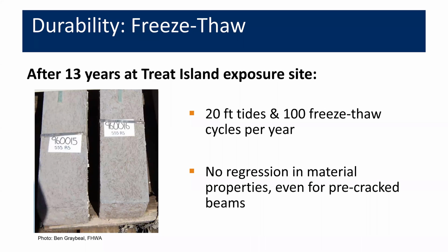And again, I mentioned earlier that we don't typically include air entrainment in UHPCs, but they do have this ability to resist the freeze-thaw distress as a result of its high strength and the low porosity that keeps the moisture from moving through the material.